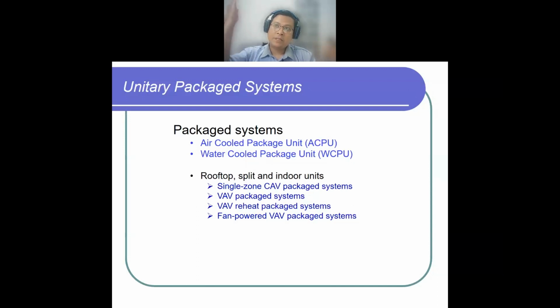For example, our office: we already considered constant air volume, so we cannot vary it. Based on the calculation, the number of occupants is maybe not more than 5%, so we cannot consider a lot of people. So we can use constant air volume.